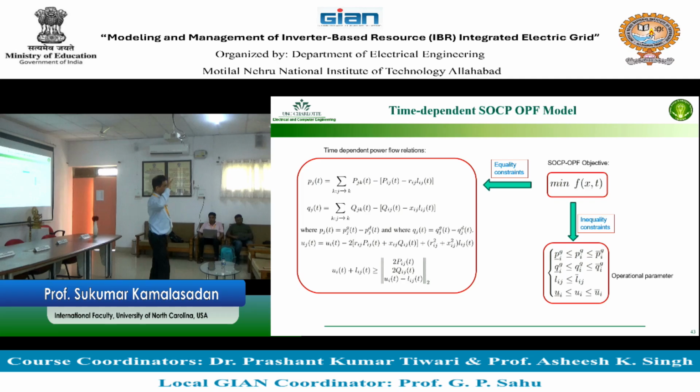You don't have to think about very detailed things, but you can actually develop a power flow like this. But when you try to implement a power flow in real life, it doesn't have value if you don't run it continuously with respect to time. Run it, after 10 minutes run it again, then the power flow has a value. If you are going to run it in an electric grid, you have to run the power flow multiple times. Running it multiple times with the same numbers given to the power flow, is there any value? No.